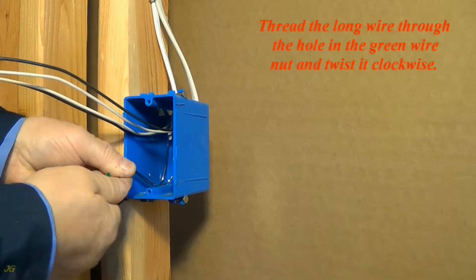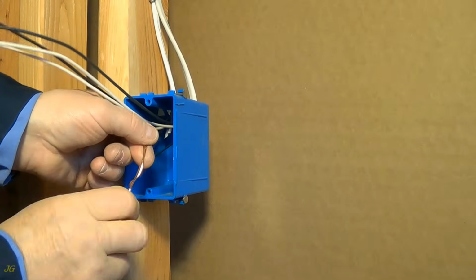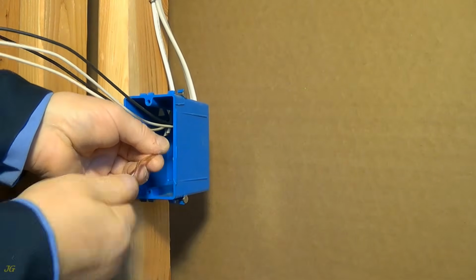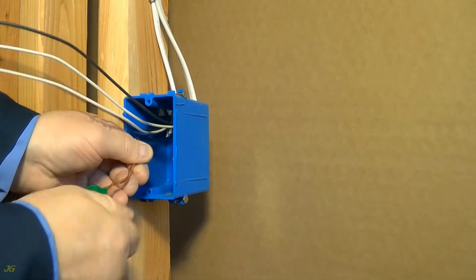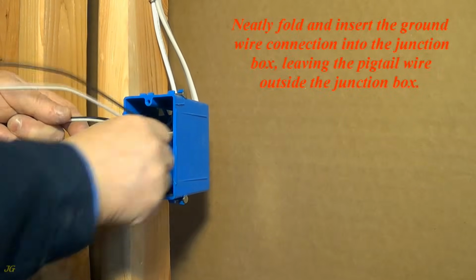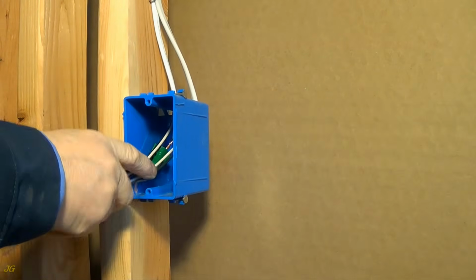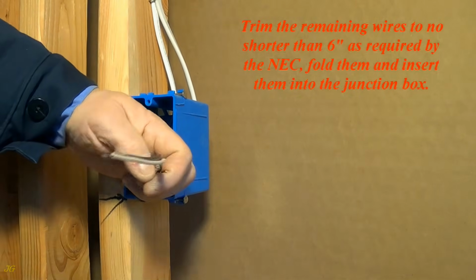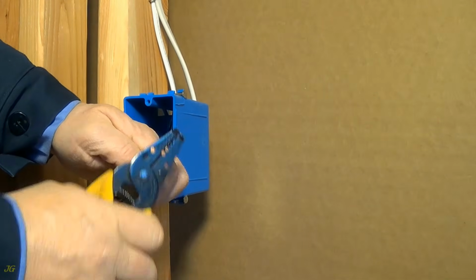Thread the long wire through the hole in the green wire nut and twist it clockwise. Neatly fold and insert the ground wire connection into the junction box, leaving the pigtail wire outside the junction box. Trim the remaining wires to no shorter than 6 inches as required by the NEC, fold them and insert them into the junction box.